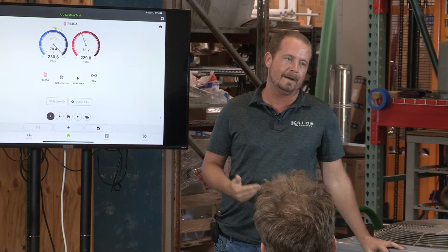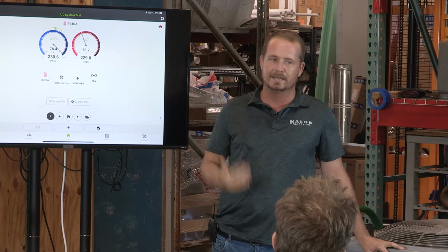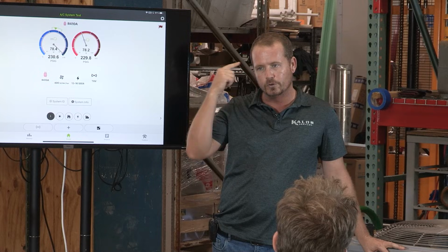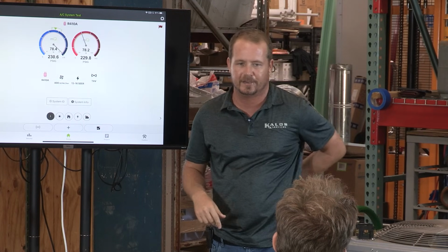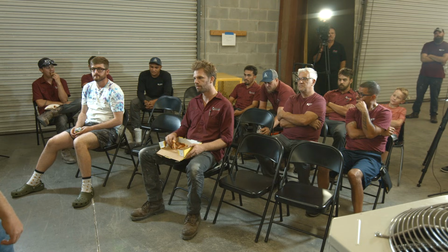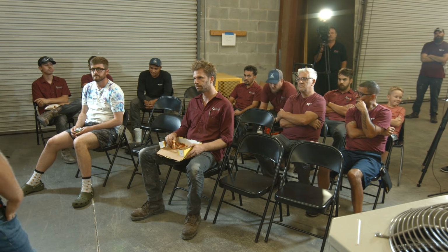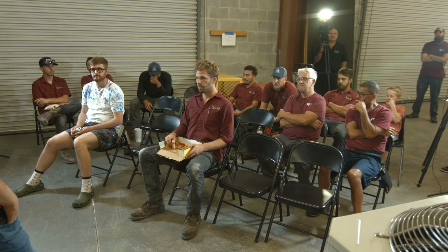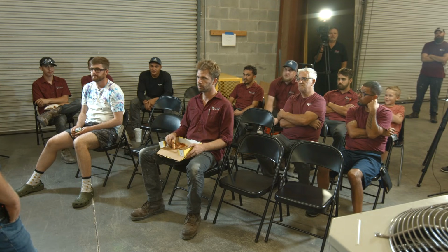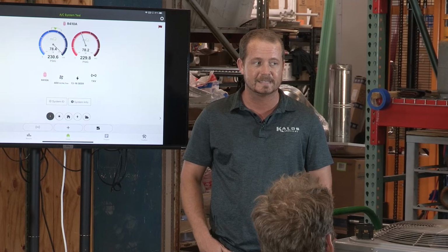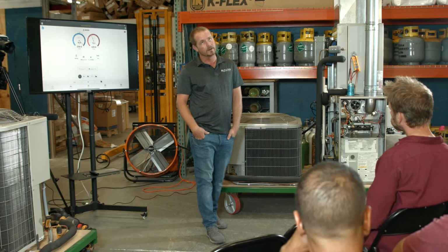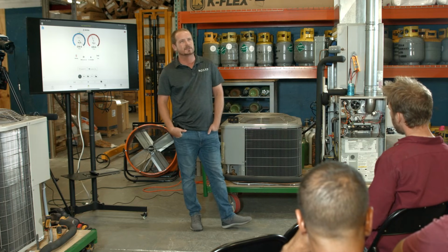So let's say that we have an old school PSC motor and you hear it making a noise. What would an experienced technician think? I'm just going to wait. I'm not in a hurry. That it's overamping. Okay, possible, but that's a symptom, not a cause. Wired incorrectly? Probably not as far as noise. Probably not on a PSC.